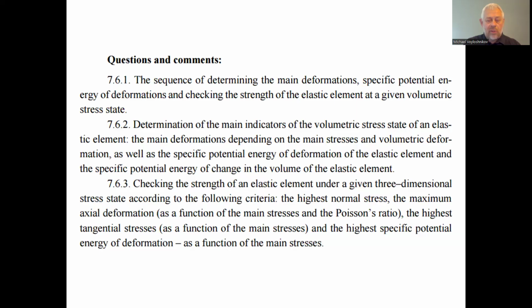So first we usually have to determine the angle of inclination, and the formula, as you remember, is the tangent of double the angle of inclination equal to 2 tau divided by the difference of the 2 sigmas, etc. After that we find the magnitude of the main stresses as the sum of the 2 assigned stresses divided by 2, plus 1 divided by 2 multiplied by the square root of the mathematical expression dependent on the tangential stresses, etc. We have the main stresses as well.